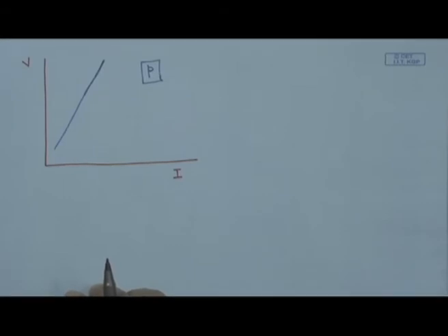That means, with a small value of voltage, with a pressure range which is very favorable to get one of the very best structures of the sputtered coating, one can get a high value of cathode current. So, this is one of the requirements in the design of the sputtering system.